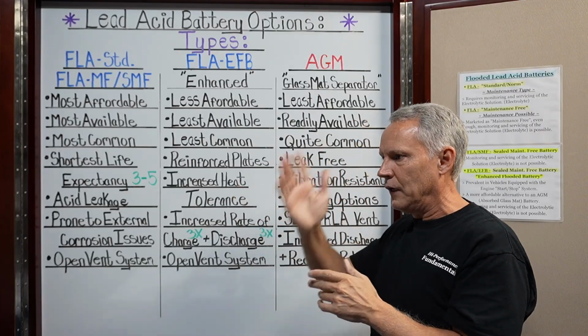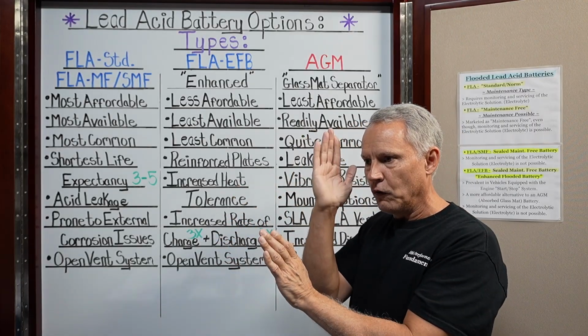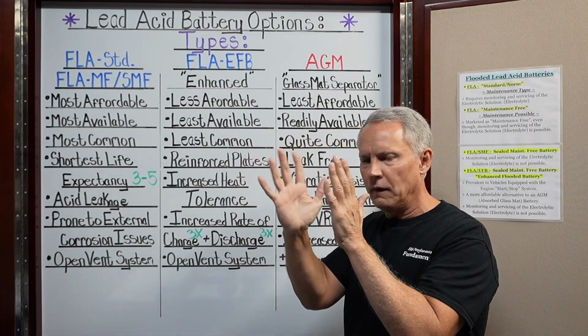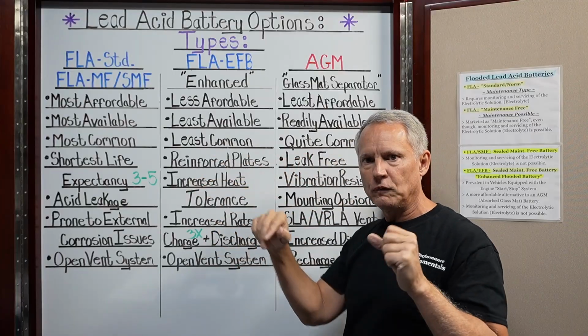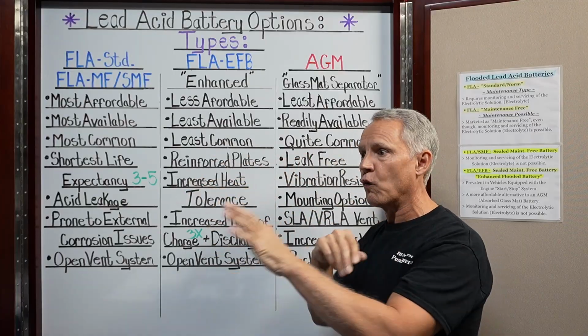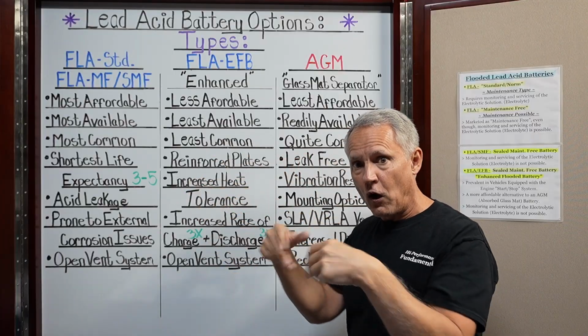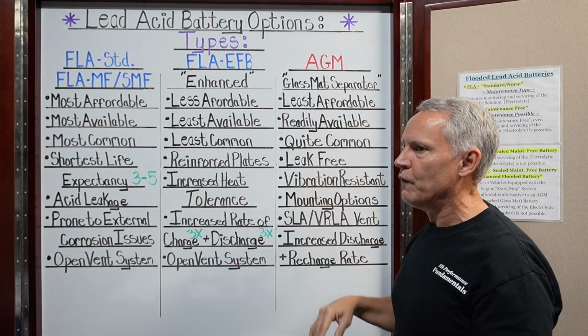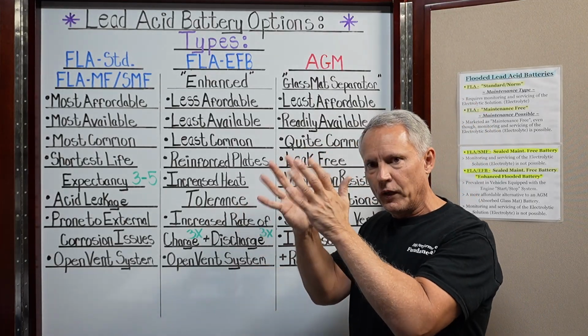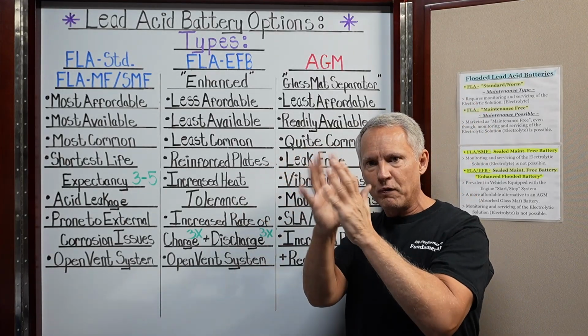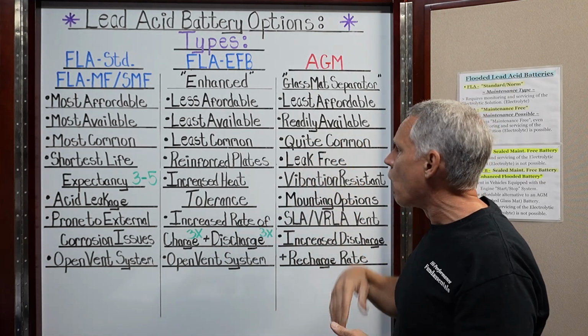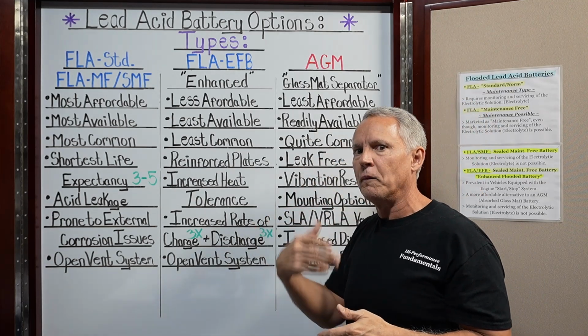So now the liquid electrolyte is suspended, and the plates are not moving around, so you don't have this sulfuric acid literally sloshing around the plates. It makes the battery very vibration resistant, so the plates aren't really affected by the vibration, and it gives you a longer life. The battery tends to last longer, it becomes more durable.